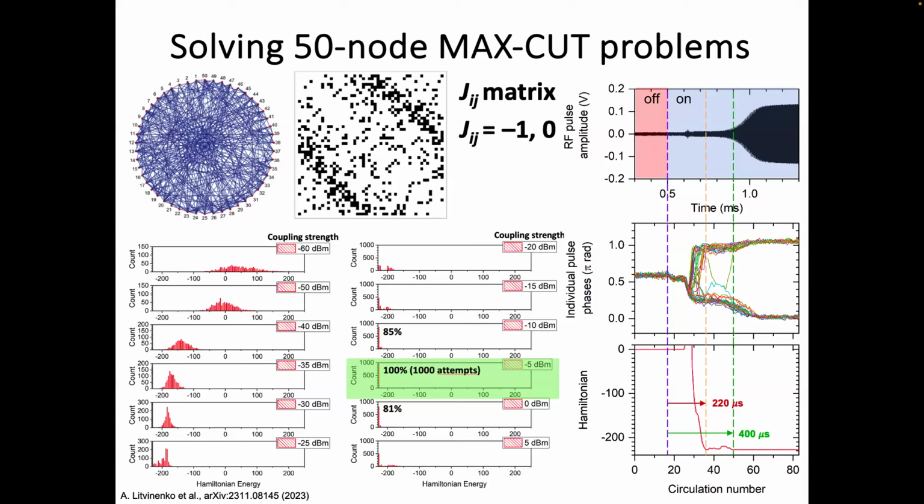Could you deliberately choose a microwave amplifier that has stronger nonlinearity and is designed to be used as a parametric amplifier? That would be a solution. Yeah. So off-the-shelf amplifiers that we have tried worked for 3 gigahertz and worked for 300 megahertz. That one particularly did the job. So 20 megahertz, no, it didn't work.